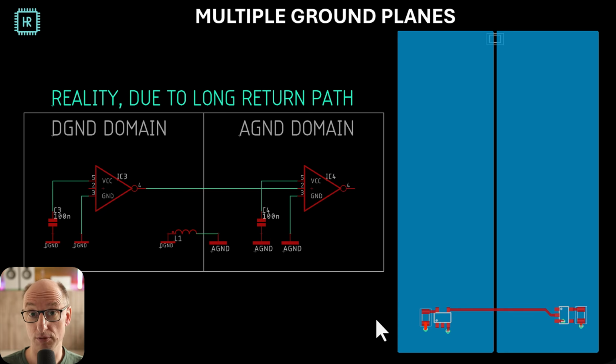Let's explain a little bit about common mode interference. Basically, you always have common mode currents running in your board, almost always. And this is going to run through your ground plane. Now, let's assume there's a common mode interference Wi-Fi signal, because everybody has Wi-Fi, going through this ground plane.